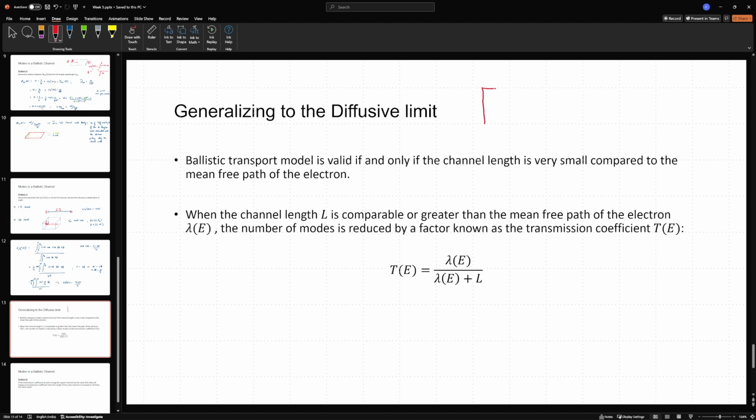When we consider conduction in bulk materials, what we essentially do is we consider the following. We will take a small slice over here, and then we will say there is a charge density rho of x, and then there is a charge density, this length is delta x, and then I will have rho of x plus delta x, and we will essentially say I is equal to some diffusion constant D_n times minus rho of x minus rho of x plus delta x divided by delta x, where rho is the charge density.